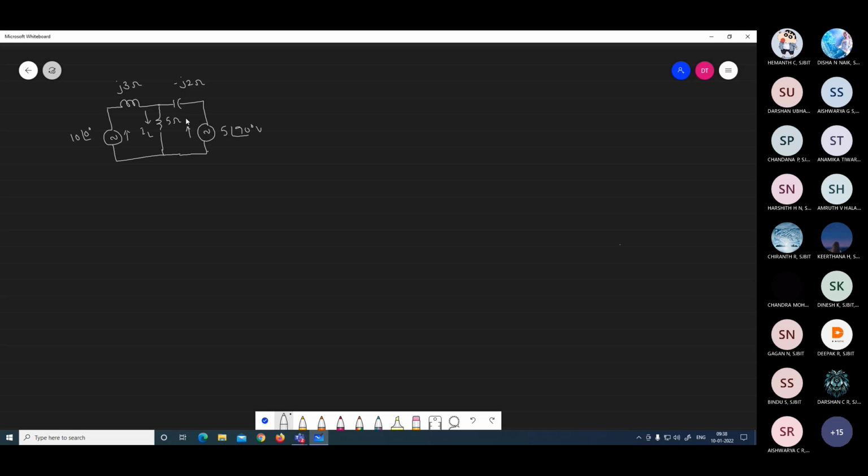In this circuit, you have to find out the current flowing through IL by using Norton's theorem. That means here the load resistance will be 5 ohm. What is the procedure to follow in Norton's theorem to find the Norton's current? Short the load terminals. Redraw this diagram.